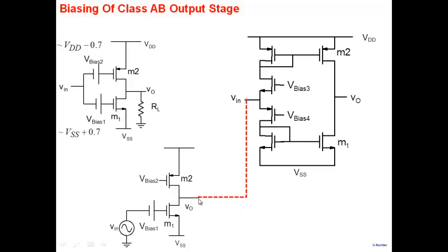If I just connect it here, remember earlier the resistance was R01 parallel R02. Now at this stage, when I look in here, what do I see? 1 over gm, 1 over gm. So the entire gain of my previous stage collapses. It's supposed to build up gain here, and the gain collapses because of this connection.